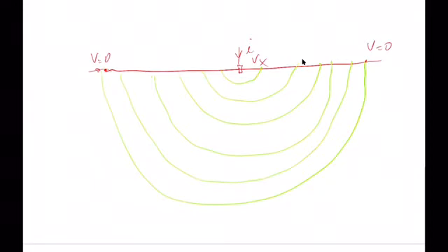So you can see the minimum is at 0 there, and the maximum is at both ends, left and right, because we just make the infinite soil, the infinite plane, into a hemisphere, because there will be a voltage drop to 0 on the surface as well, rather than infinite voltage everywhere. So you can see the voltage is reducing in steps like that.